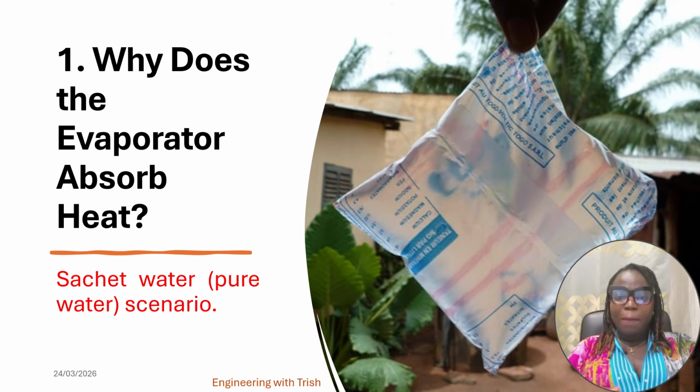When this happens, the refrigerant changes phase. In fact, we say superheated refrigerant. This superheated vapor leaves the compressor and goes into the condenser. The condenser, like we know, is a heat exchanger, which means the temperature of the refrigerant is now very high compared to the environment. So the heat will spontaneously flow from the condenser to the environment.